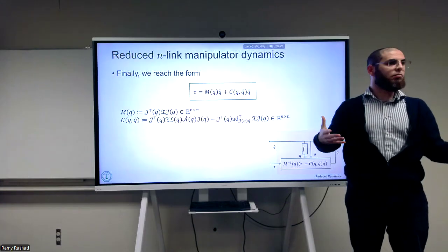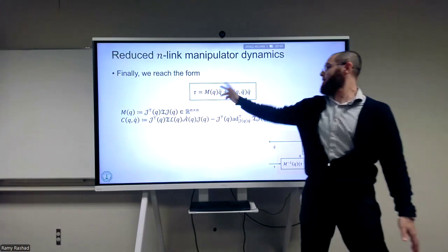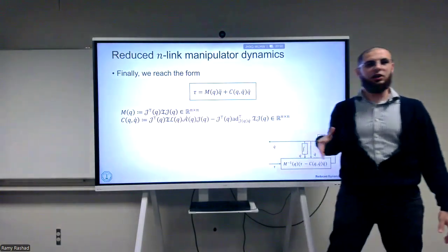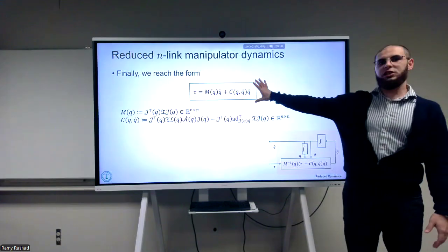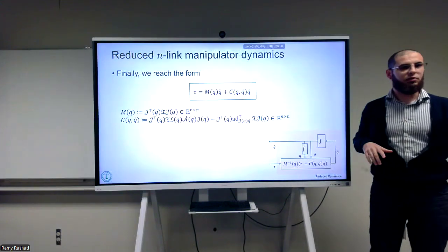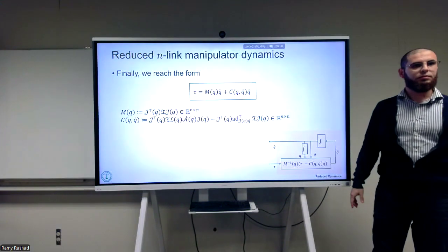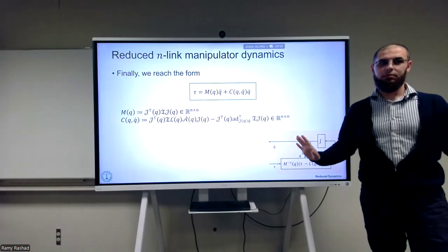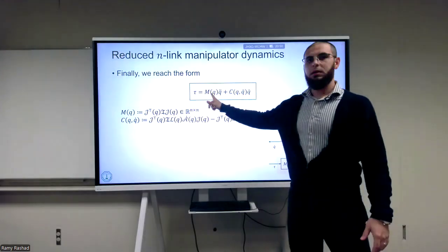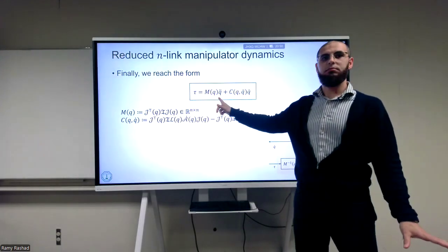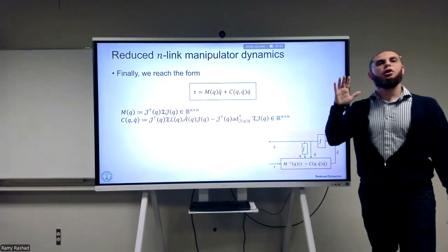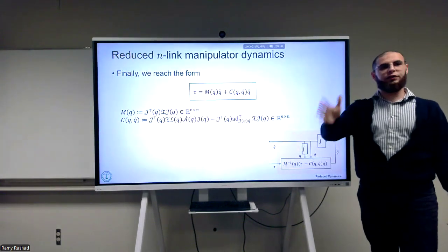Of course, they're nonlinear. They're highly coupled, so the M and the C. You don't expect this to be diagonal, okay? So this is highly coupled. But in the end, we've just done the differential equations of the robot. So we assume it's linear differential? No. The M is completely nonlinear. So this is a nonlinear, ordinary, second order differential equation.